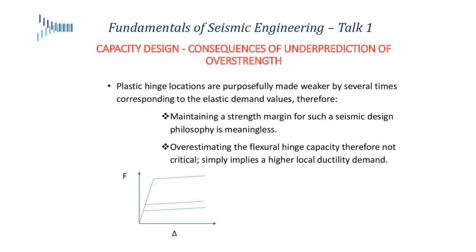Now, let's come back to the point I was making earlier. So we said that if we overestimate our capacity for gravity, that's bad, and we understand that. That's not the case when it comes to seismic, I had said. So this is a system which was much more strong. Okay, so I want you to focus on this diagram for a second. This would have been the elastic demand in the system if I had just designed it elastically. I'm assuming it has some ductility, so I've drawn this horizontal line.